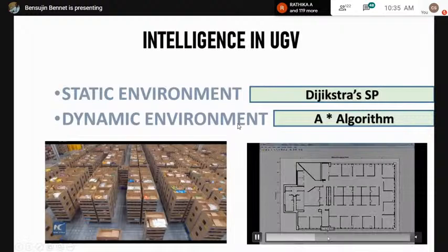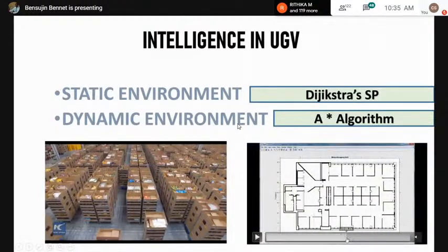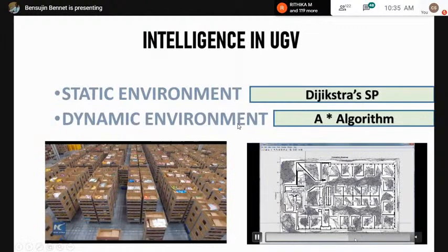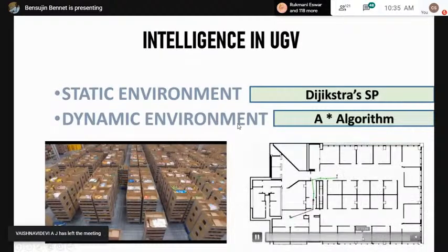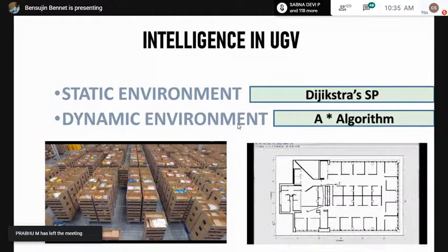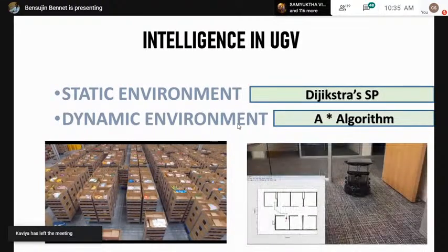In MATLAB, you can see an algorithm called the pure pursuit program. There is a module called the pure pursuit module, which will create the path for the robot for us. After you do this, it will decide the path, and the robot will move in the occupancy grid. So this is a small demonstration of how we can do it with MATLAB.